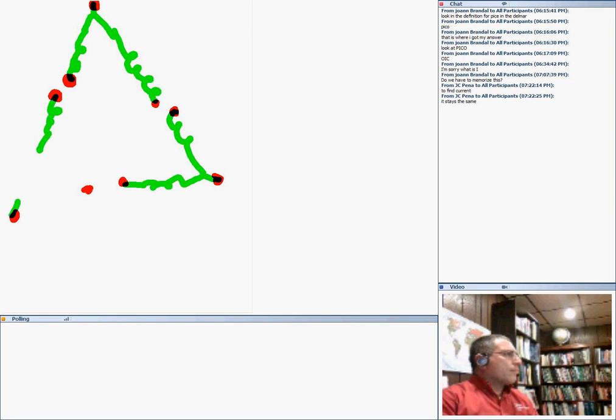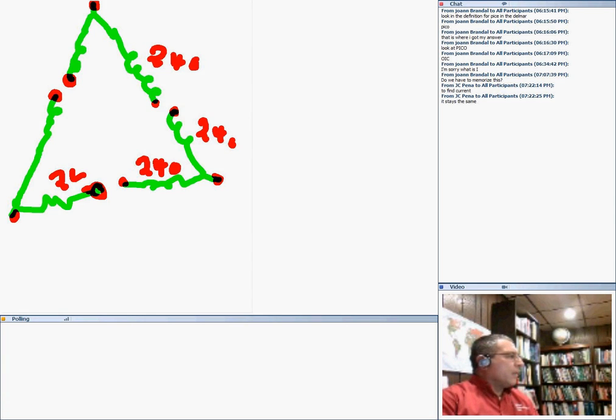So grab my lead here and grab it here. This is the coil. And grab this one coil and back into my ring. Okay. Can you guys see how many leads? 9 leads. Now, look at that. This coil would be a 240 coil. Each one of these coils is 240, rated by manufacturers for 240. This is a 240 coil, and from this side is a 240 coil, and this side is a 240 coil.